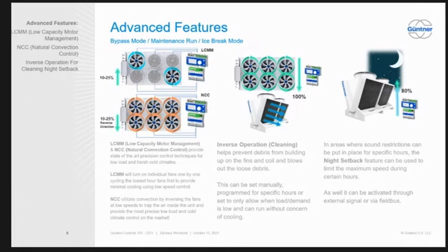If you guys aren't familiar with what we're talking about, I know we've talked about this subject on many a podcast, but typically nowadays we like doing 0 volts as 100%. And the reason why is because if God forbid you lose your analog output coming from your controller, at least if it shuts down in the fail safe, all your fans are on.